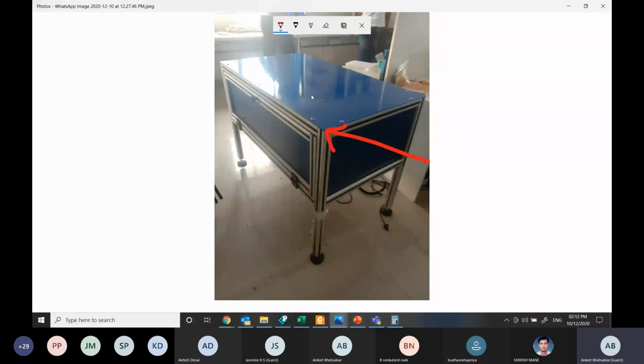So if you are applying some pressure, let us consider you are mounting some Mitsubishi robot onto this plate, and it has some 40 kg weight, because of this it will have some deformation. There will be some deformation in the plate. So now you can simply visualize what the deformation can be. It will have bending of the plate. That same behavior you will get in mode shape 1.